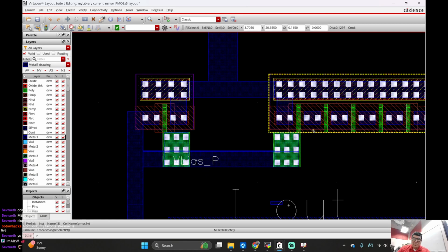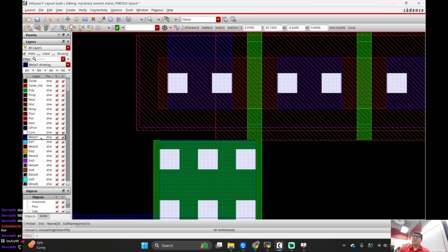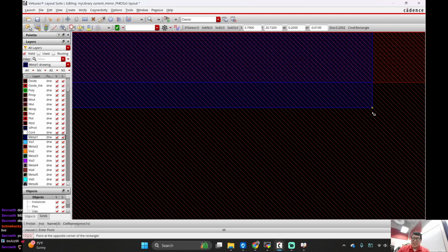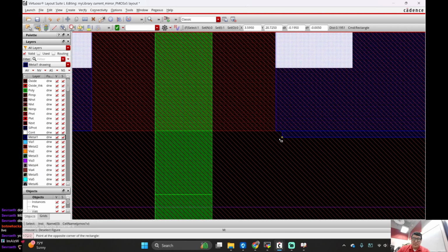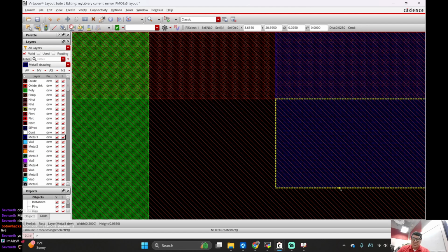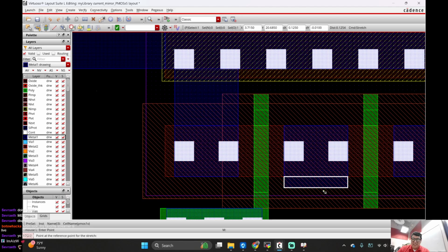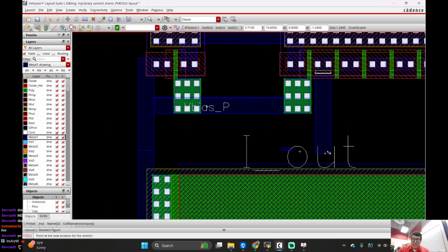Anyways, what I'm going to do right here is draw metal 1. Someone drew on oxide and did this, and I was like, why? Don't do that. Click on metal 1. This is how I do layout design. Oh, come on. There we go. Zoom in a little bit. Then I stretch. S to stretch. There we go. Okay, stretch this out, right?